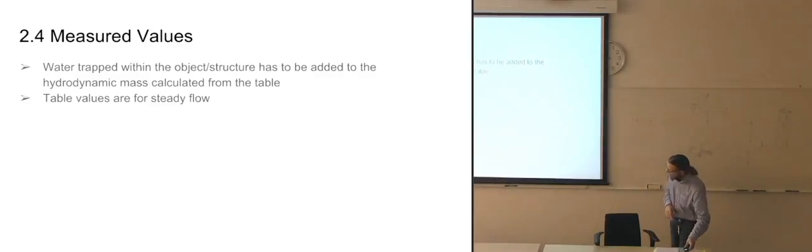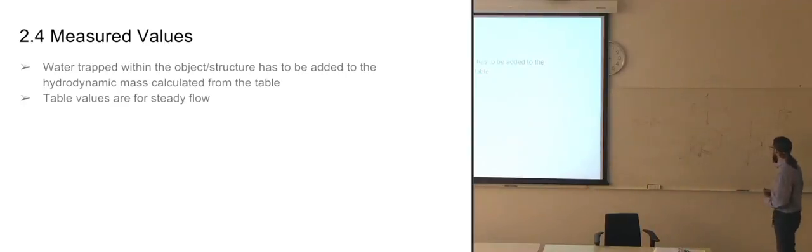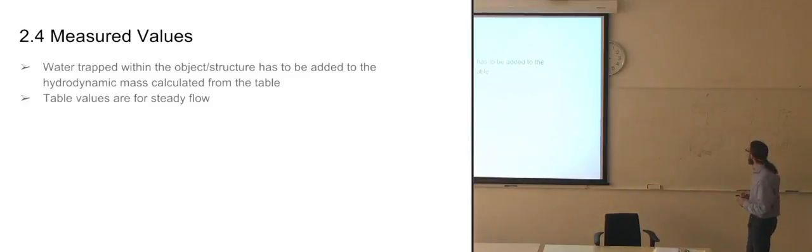So if you are lowering, for example, if we're lowering this plate down, and you also have heave motions as you are lowering, then you will have, on the wire coming down from the crane, a certain velocity. And that one will be constant. So V1 will be constant, for an example, 0.3 meters per second, slow lowering of it.